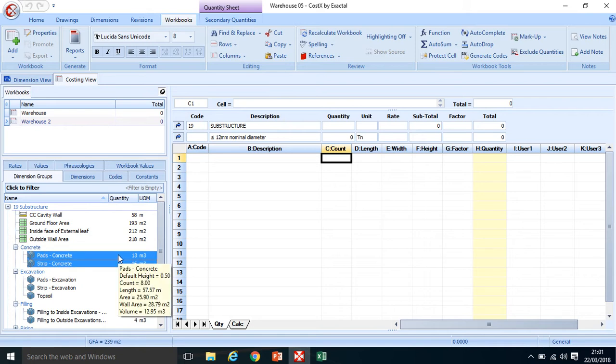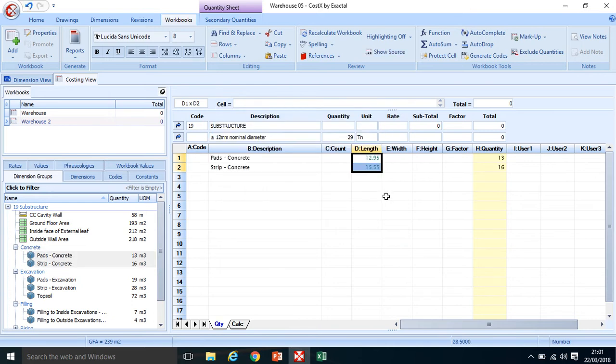of concrete pads. So again, select those 2 items, drag and drop them into length, take them as a volume. So I've got about 29 meters cubed there in total between those 2 items of concrete, and the rule of thumb I'm using is 150 kg of steel per 1 meter cubed. So I'm going to multiply, it doesn't necessarily have to be a width, it's just one thing multiplied by another, and that gives me 4,275 kg. So to change that to tons, I divide it by 1,000 or multiply it by a factor of 0.001, which is the same.